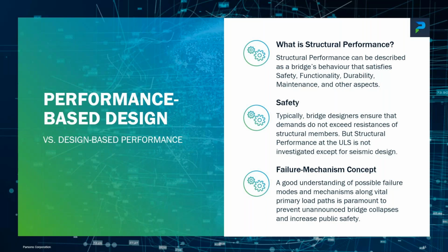Think about a pushover analysis, where you push the bridge to its limits in order to see what the displacement capacity of the structure is when, for example, on a frame, the P-delta effects kick in and basically the bridge goes on its own. So you want to understand the limits. You may never reach the limits in a typical ULS scenario, but you want to understand them because this understanding is so essential for designing better bridges.